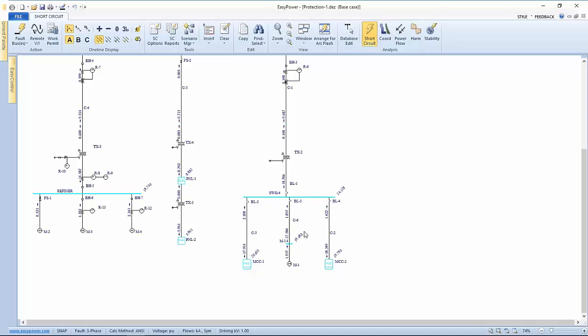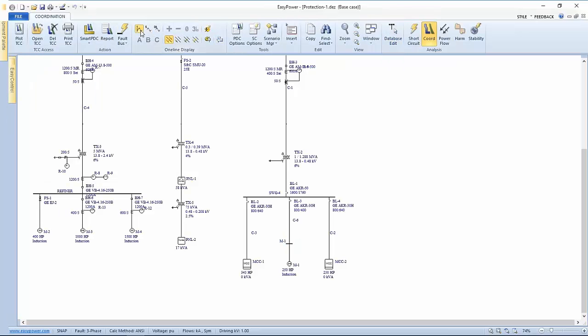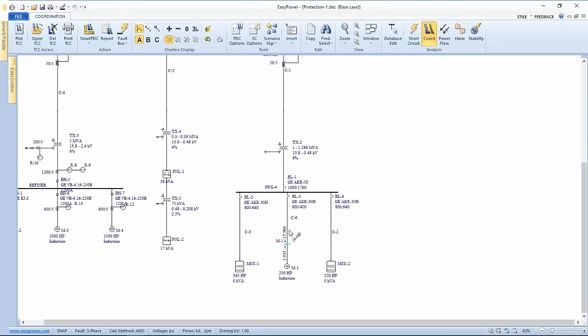All right, the point here is what happens if this particular bus faults? What happens to the tripping devices upstream? So I'm going to go to Coordination Focus. I'm going to look at currents, not energy. I'm going to three-phase bolted fault. I'm going to fault a single bus. And again, because I didn't have a bus selected, it faulted everything, so I'm going to go back and fault this single bus here. And what I see are branch currents for that particular fault.